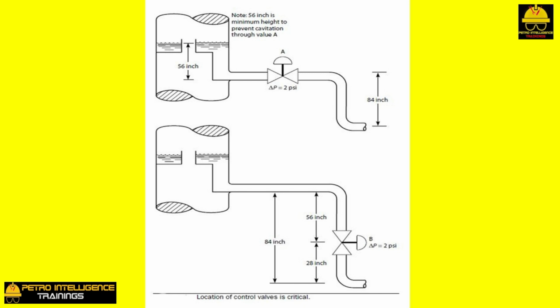Let's assume that the increase in velocity through the draw-off nozzle is small, and hence the nozzle exit loss is zero. The frictional loss through the piping and nozzle is zero. Even after we have made these two unlikely assumptions, the height of hot water in the draw-off sump must still be 56 inch above the center line of the draw-off nozzle.